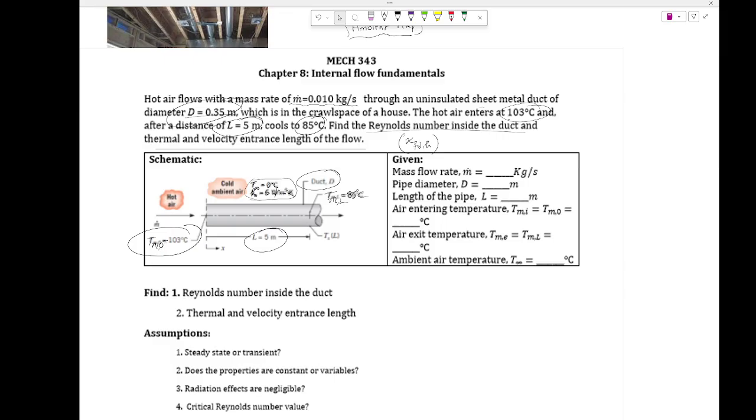Usually not that much flow happens. You can expect this is natural convection. And usually forced convection, that's why you're doing the experiment, you'll be seeing it. When you get the h value, it should be more than 10, 20 or something. The free convection values are usually very low. The 6 watt per meter square Kelvin given is kind of saying that free convection is happening.